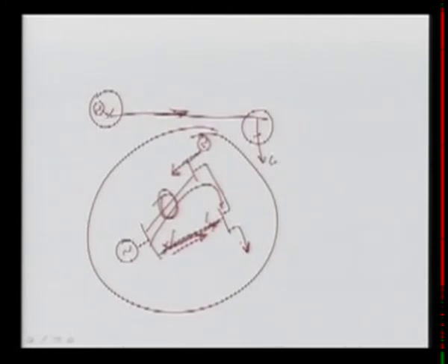There will be some protection system, that is overcurrent protection or distance protection. What will happen? This will also be tripped, and there will be cascade tripping, and the whole system will be in blackout. So with the help of controlling, if there are other lines, we can control easily, and then we can avoid the blackouts in the system.